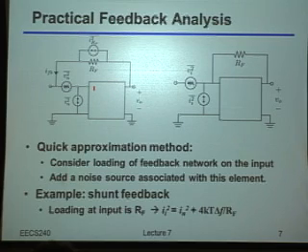Okay? So the idea is that if I've added this resistor, and I look at its effect on the input, well, because I've put this thing into a shunt feedback configuration, again, my input is essentially going to be in the current domain. Right? So if it's in the current domain, what I'm largely interested in is how much current this feedback resistor basically drives directly onto that input. And as usual, we could just model that as being 4kT delta F divided by that feedback resistance.